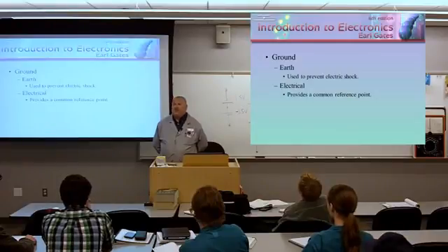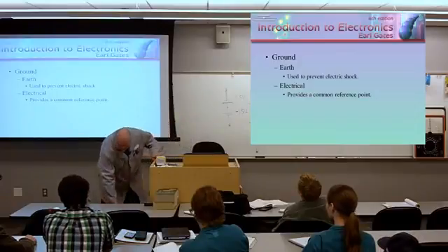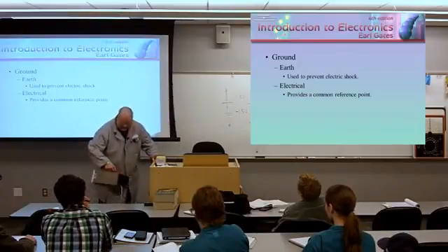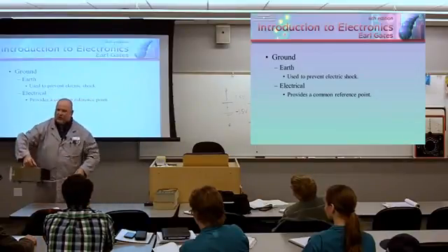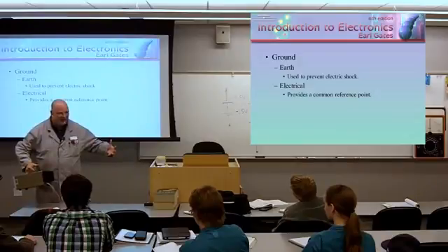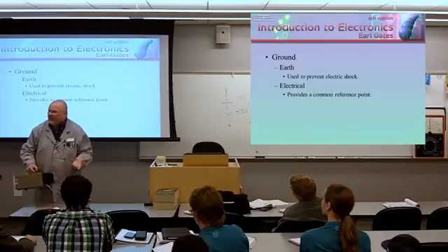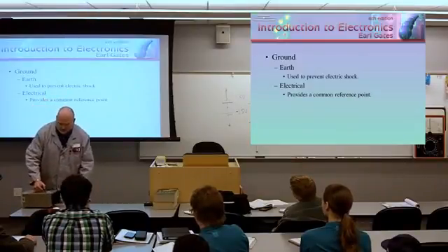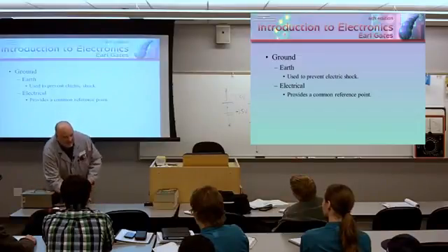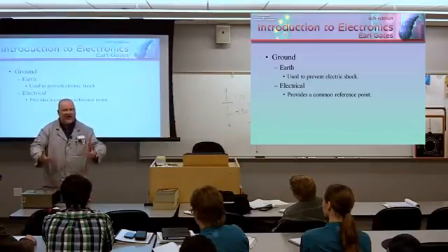You might get into a piece of equipment and say, oh wow, look at this big metal. This is actually a DC power supply like we use in the lab, okay? This in the back here is a heat sink. If this was installed inside some big piece of equipment like a radar system, you see this metal, you assume that, oh, this metal here, that's ground. That must be ground because it's metal, right? And all of a sudden you put your hand on there, or you lean into it, and you get electrocuted.